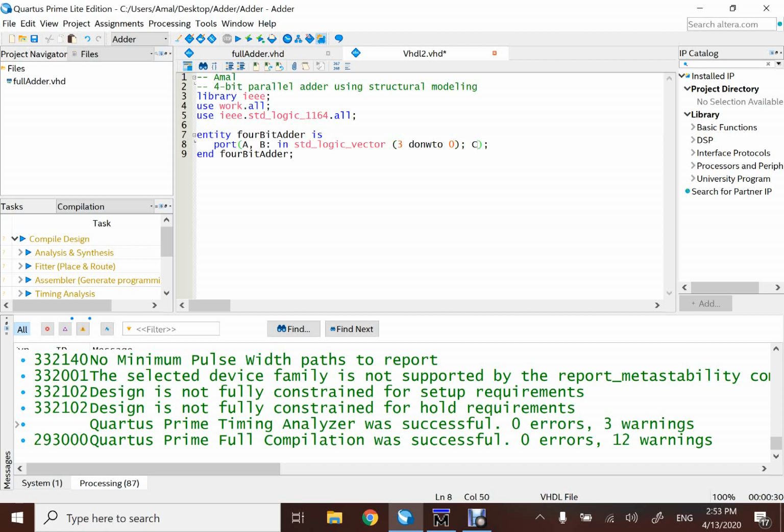The third input would be Cn. Cn is an input. You could name it Cn if you want, or Ci. I'll use Ci. It's an input of type 1 bit. So standard logic is good enough. I'm gonna expand this here a bit. It's not allowing me, it's fine.